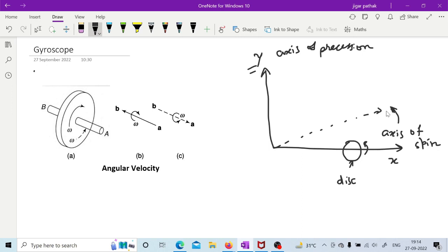That direction will be along whatever third axis is remaining, which you can consider as normal to the plane of this screen. That particular couple is known as the active gyroscopic couple, which will try to rotate the object about this third axis. Whenever an active gyroscopic couple is there, there must be a reactive gyroscopic couple also, as you have centrifugal acceleration and centripetal acceleration.